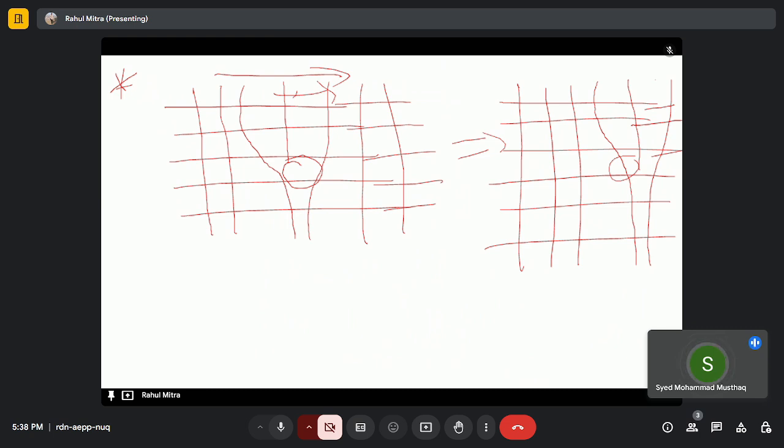But in the case of dislocation motion, only the extra half plane bonds are being broken, and the planes surrounding the dislocation, like 3 to 4 atomic planes, are being distorted. That is the only energy required for the formation and motion of dislocation, right? And this is the edge dislocation.